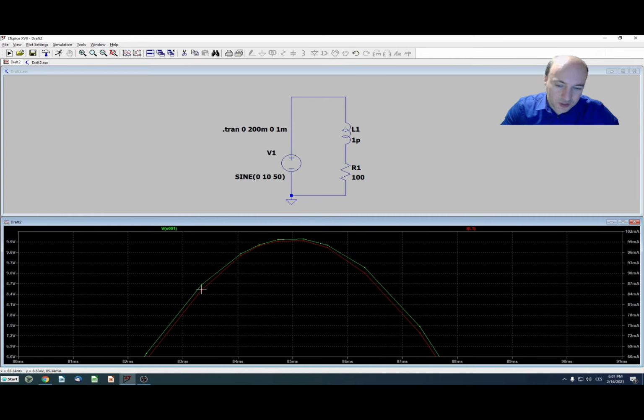We can see those small dots are where it did calculate the result, and those lines are only a connection in a linear way. So in fact our circuit was calculated only in those points. I can have a more accurate simulation if I decrease the sampling time of a calculation, but we don't need that here in our simulation.